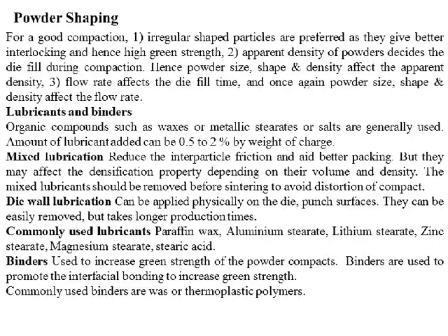We require a proper shape of the powder for a few reasons, like good compaction. For good compaction, we usually require irregular shaped particles. Why are irregular shaped particles preferred in powder metallurgy? Because these particles bind properly, or interlock properly, and improve the strength of the component.